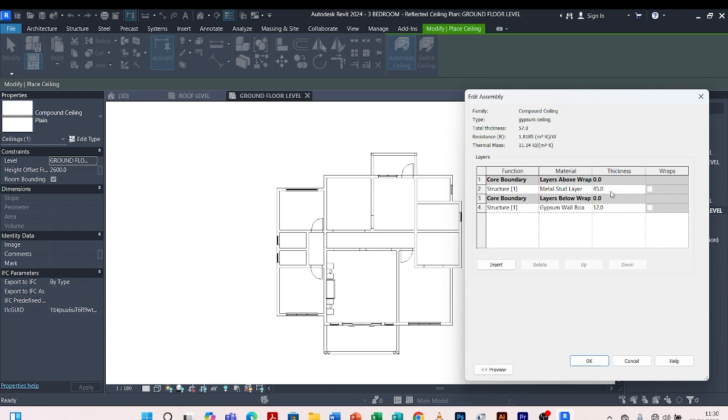I can make it 50 millimeter thick. So I can give the finish, that is the lower finish, can give it 10. Then the structure, that is the material, I can give it 40 to have a total of 50. Let me move this one up. I change this to finish. Then this structure. So for the finish, I can have it as just concrete maybe.